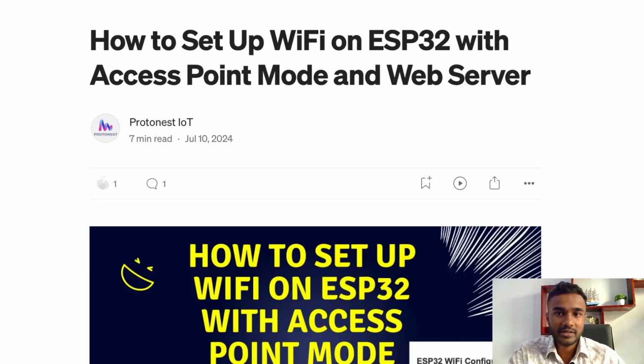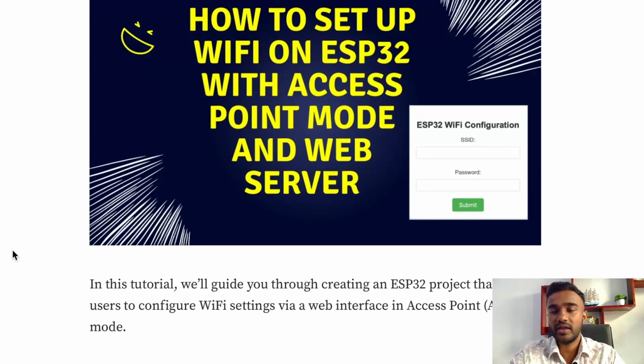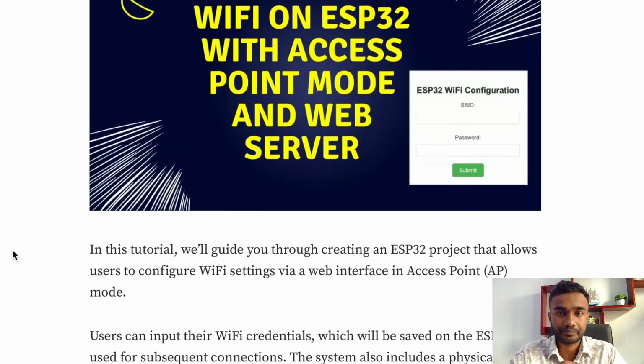Another method is the one that we are explaining in this video, using access point mode and a simple web server. Here we have a simple UI for you to add your credentials as SSID and password, and then submit it. Then the ESP32 will be updated with those credentials.